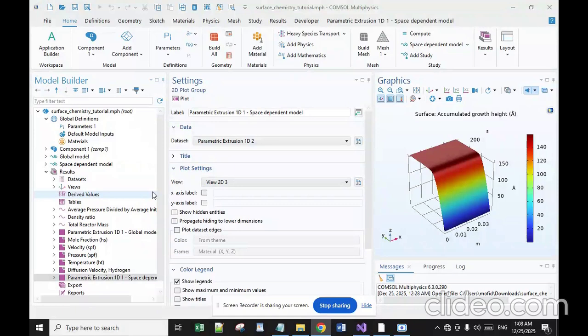Model definition: this simulation model simulates outgassing from a vapor during a chemical vapor deposition (CVD) process. Careful attention is paid to the overall mass balance in the system, and the difference between the mass average velocity and diffusion velocity is explored. The same physical problem is investigated first with a global volume average model and after with a space-dependent model.